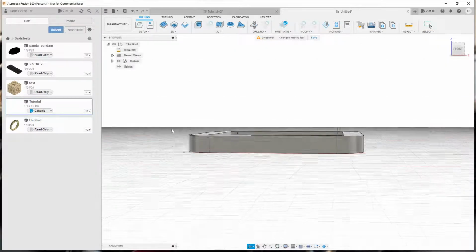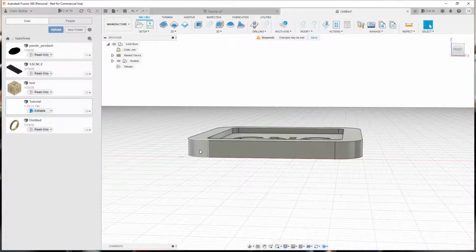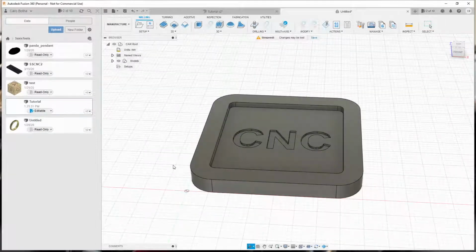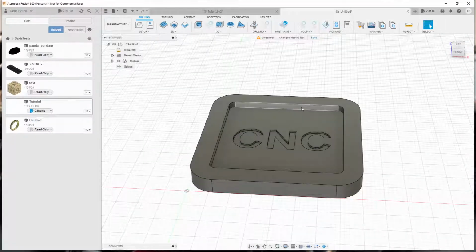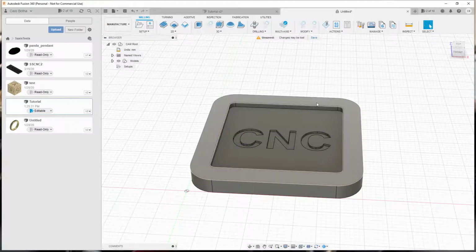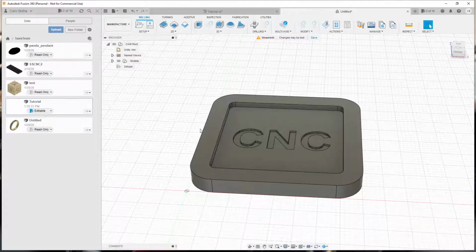We may have put a bit of stock onto the machine. I think I made this 4 millimeters. So the stock may be 4.2 or 4.3 mil. Maybe it's not even. Maybe it's 4.5 on this side and 4.1 on this side. We just want to face that surface area, get it nice and clean to start the machining. Facing is going to try to stay within this curve.